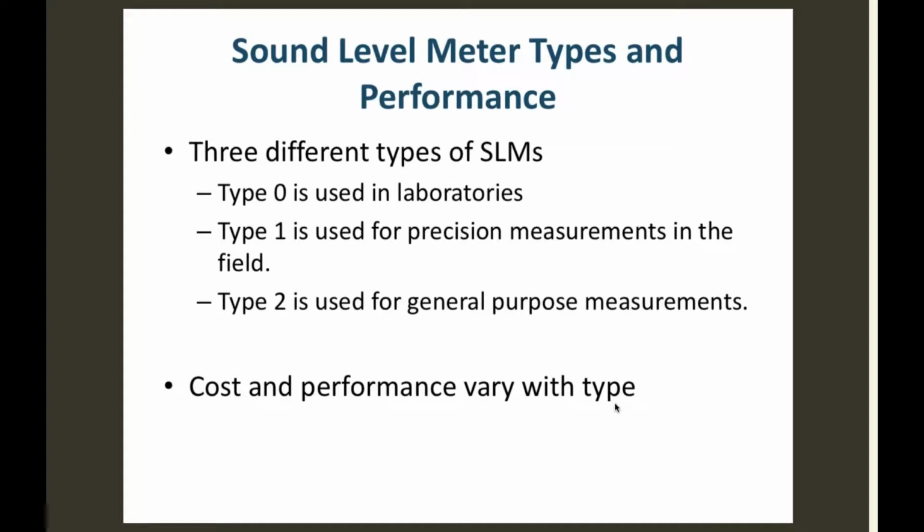Oh, you got both. And dosimeter means anything that measures the dose that a worker is exposed to, right? So it could be a radiation dose, it could be a noise dose. They have carbon monoxide devices too, where if you work in a carbon monoxide environment, you can wear a badge that changes color as you're exposed to carbon monoxide. So if you wear that over an 8-hour period, at the end of the day you can hold it up against a chart and see what your dose was.